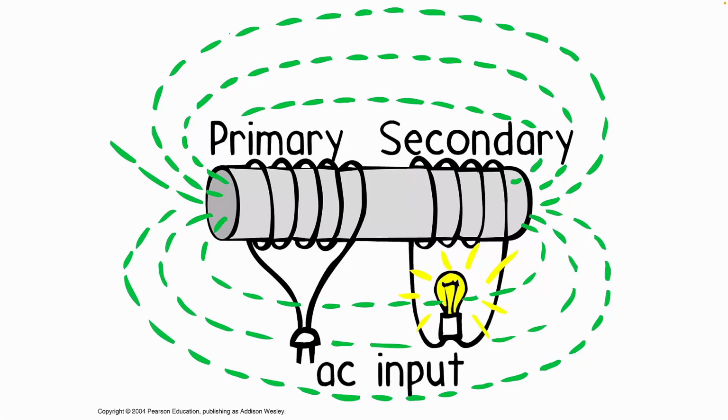And why are they connected magnetically? They're wound around the same iron core. Iron is a ferromagnetic material, meaning it responds to magnetic fields, it gets happy. If they are wound around the same iron core, what can you tell me about the magnetic flux through these coils? It's the same. Whatever flux you have in the primary is the flux that you will have in the secondary. Quite often, in real transformers, these two coils are not separated in space like we have in this drawing. They're usually wound on top of each other, in and amongst each other.